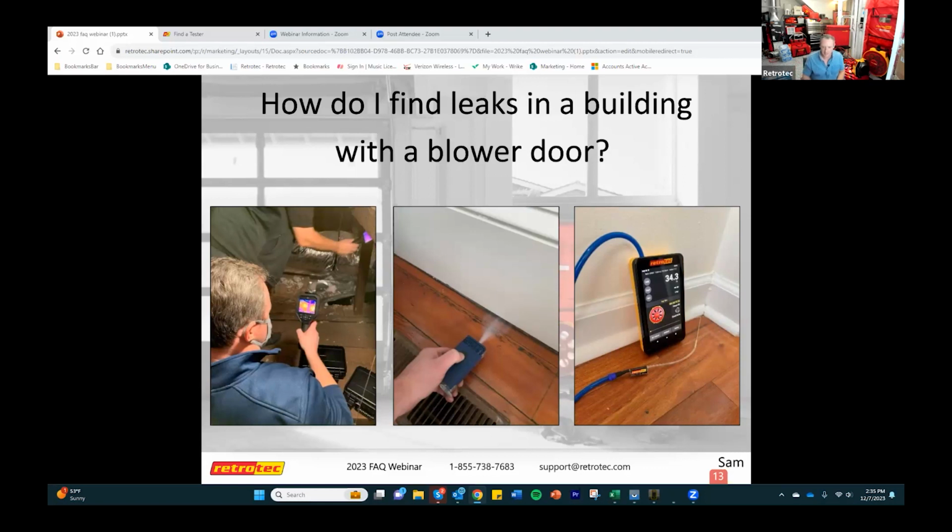So in this case, this is an elevated slab foundation that meets a crawl space that didn't get sealed at that joint. So there's air coming in up from the bottom. But we're able to get this tiny probe in there underneath the trim molding to see that. So we didn't have to drill any holes or anything. So just looking for pressure differentials can tell you a lot too. So those are my three favorite ways to do it.